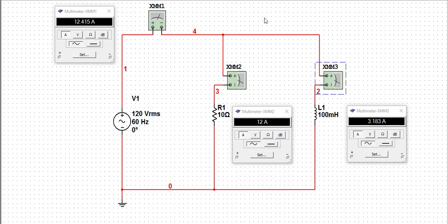And remember, that's a result of 120 volts being connected across what is the equivalent of 37.7 ohms of reactance. So if you calculate that, you'd get 3.2 amps. Now, remember, these two currents are not in phase. So we're going to find that we have an angular relationship between those two currents. And of course, that angular relationship is going to be a 90-degree relationship. So we would have the current of IR at 0 degrees. We would have the current of IL at minus 90 degrees. And then the result would be the total current that is the hypotenuse of that triangle. And we're going to demonstrate that back here on the calculations right now.